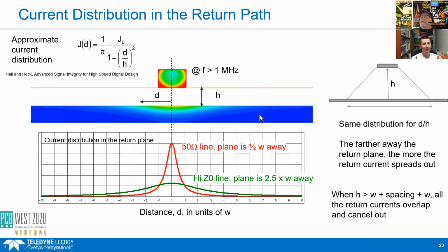And we call this... Exactly, yeah, the question I wanted to ask, because if you make a gap in the solid ground plane, then for example, multiple return paths from multiple different signals will go through the same area. And I wanted to know, what do you think, if multiple return currents going through the same area are going to influence each other and are going to make the signal worse? Very good. Absolutely right. So if you have the same inductance, same return path, will make the return path over here.